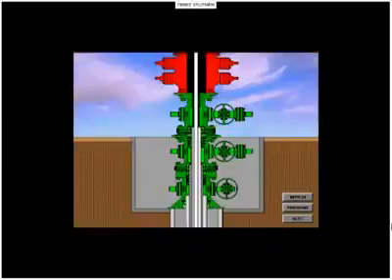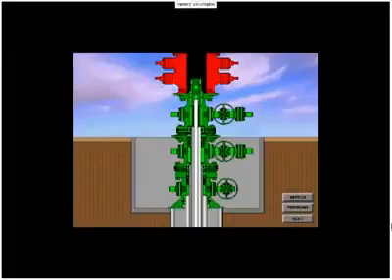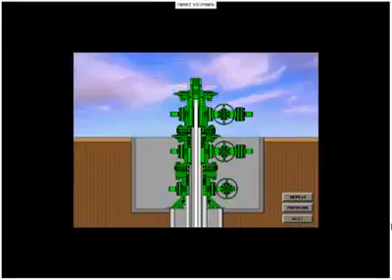After the tubing is spaced out and proper weight set on the packer, the tubing hanger is installed at the tubing on the rig floor, then lowered into the bowl of the tubing spool. The BOP system is nippled down and preparations are made to install the production Christmas tree.